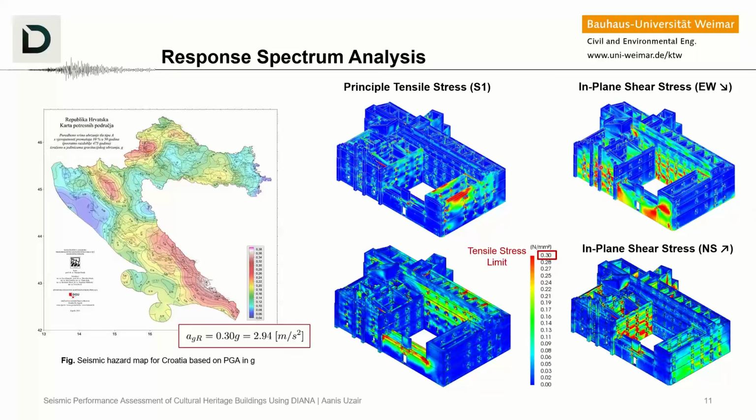That's why you would see that there is diagonal cracking, for example, from the corner of the opening, or where the facade is large and big, you see that there is a propagation of the crack, although the propagation is over a large part of the wall, because the mesh is not refined enough to capture the actual crack.